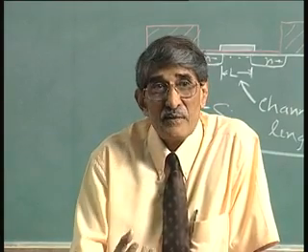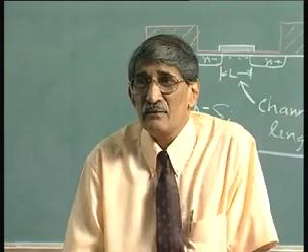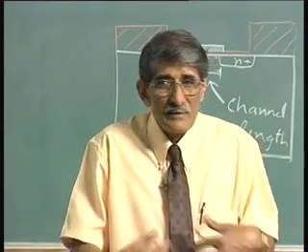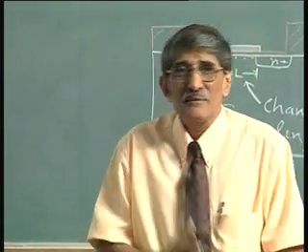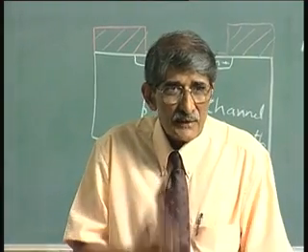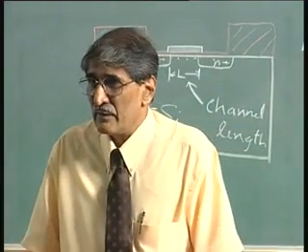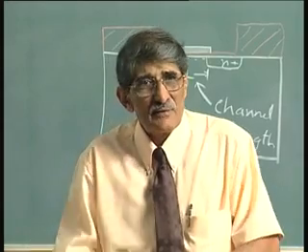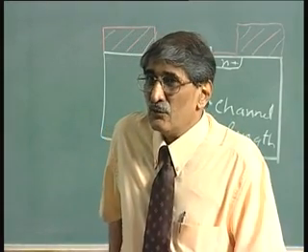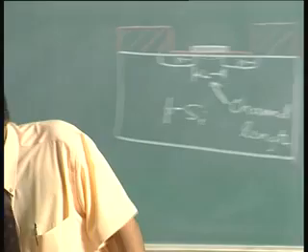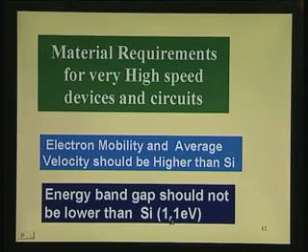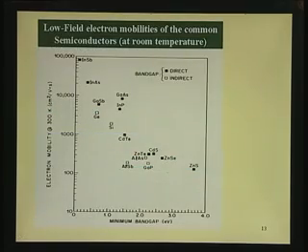So, the result is the temperature rise. So, when the temperature rises, you do not want the devices to lose their property. Junction should behave like junction. So, you can't tolerate germanium in those devices. Silicon with fan and all that you are able to tolerate. Okay. So, you are looking at materials which have band gap definitely higher than that of silicon. Higher mobility and higher band gap.